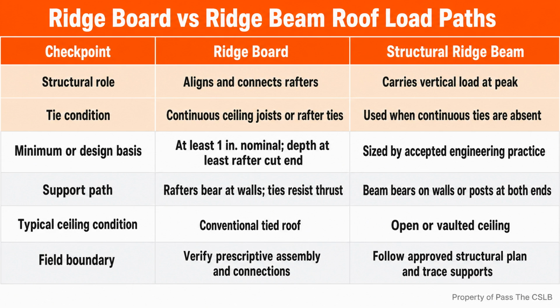Before demolition, I want the approved details, the beam specification, connection requirements, post locations, and the support below each post. I also want the sequence clear so the crew does not remove the existing restraint before temporary support and the permanent system are ready. A vaulted ceiling does not make a roof mysterious. It simply changes the route.